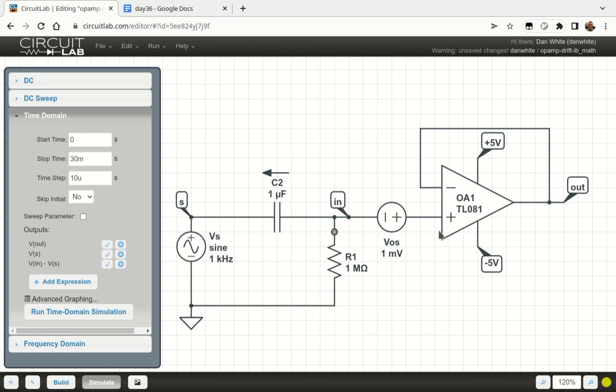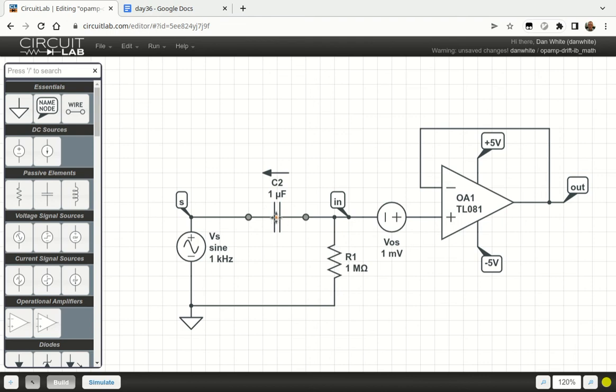Now, in general, don't presume that you know the sign of even the input bias current unless you have good information from the data sheet to know the sign. Remember that that sign is usually given as positive because we talk about magnitudes. So we have shown what you can do by adding a capacitor here to shift DC to ignore it, and then we still have to have a DC current path for our input bias current for the op amp.